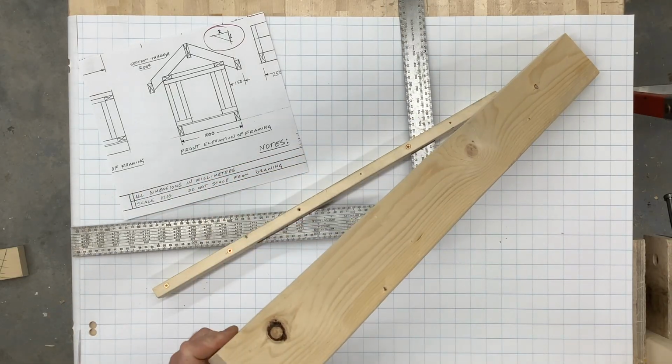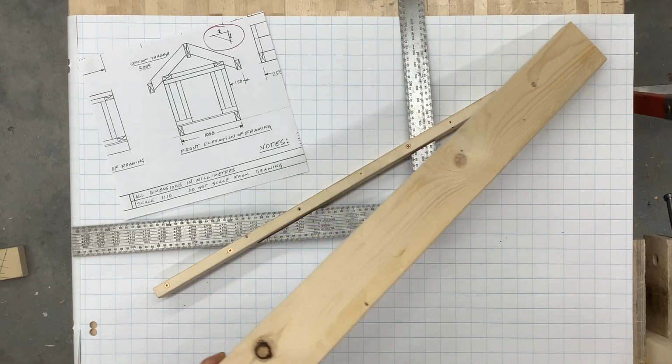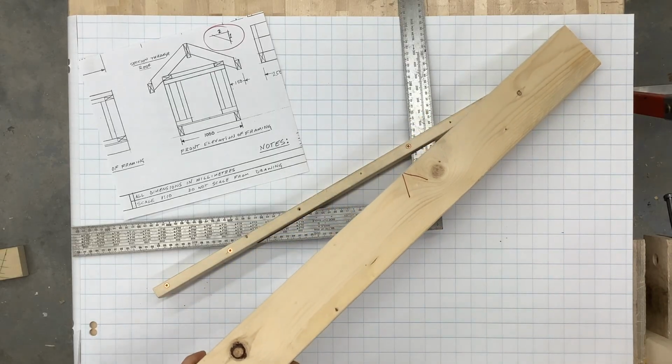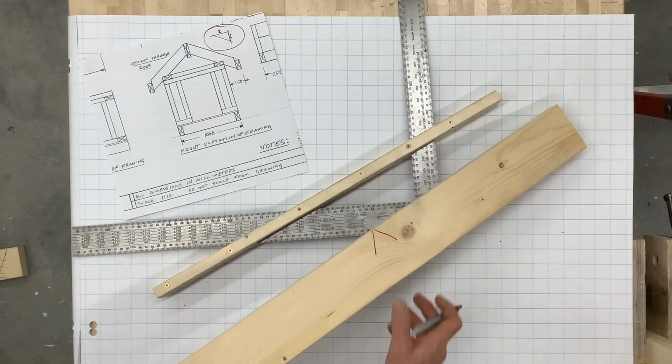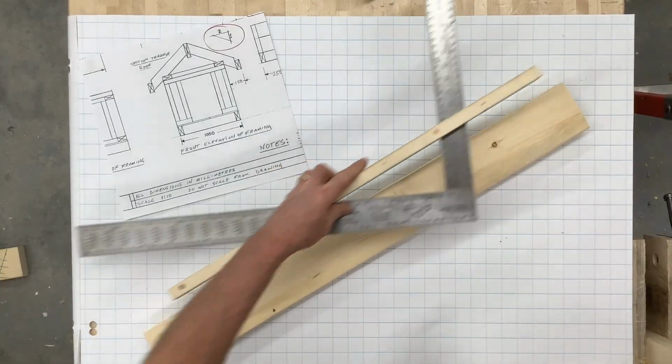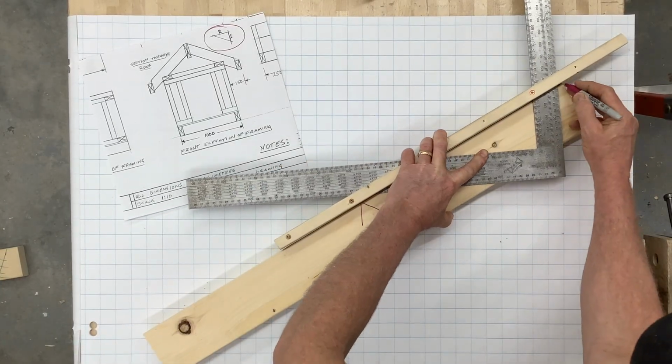Before turning a piece of lumber into a rafter, sight along the edge and look for an edgeways bow or crown in the board. Rafters and floor joists should be installed with the crown facing up so that their weight tends to straighten them as they sag.